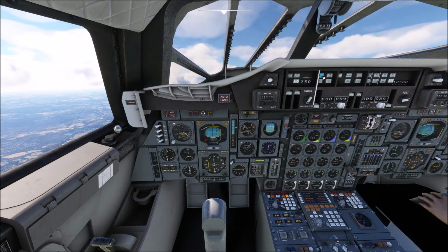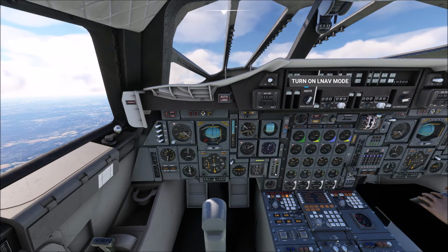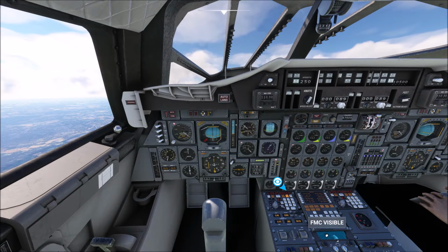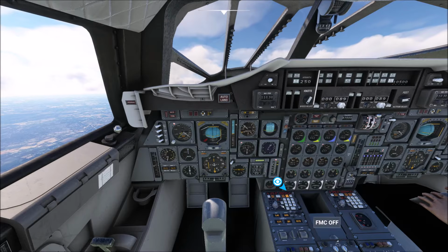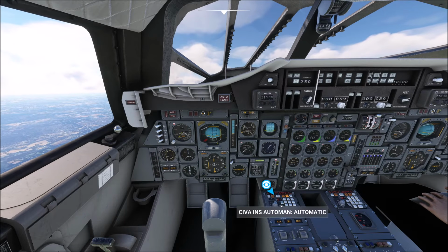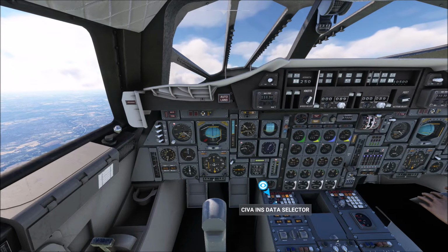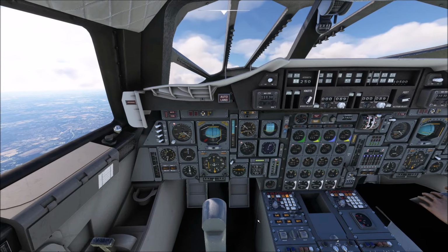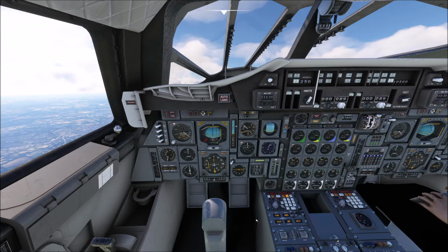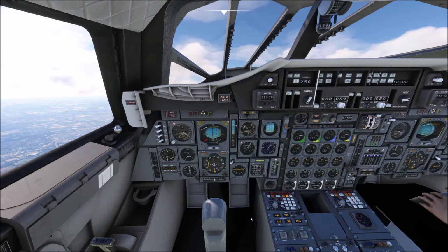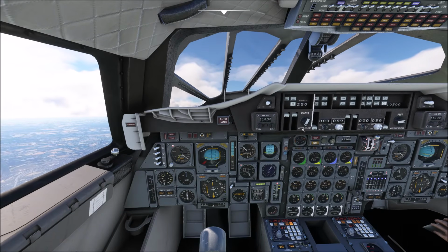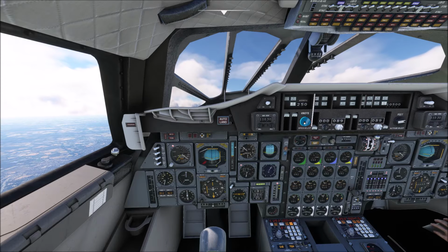And you would simply switch to INS, and that will track the exact same flight plan, but more in the manner of a modern flight autopilot. Because an INS is not really an autopilot, it's following a set of coordinates. This one does act a little bit more like an autopilot to make it a little bit more manageable, but that's not its real function. So, everything going good, everything's tracking okay. Concorde would normally clear to about 400 knots now.